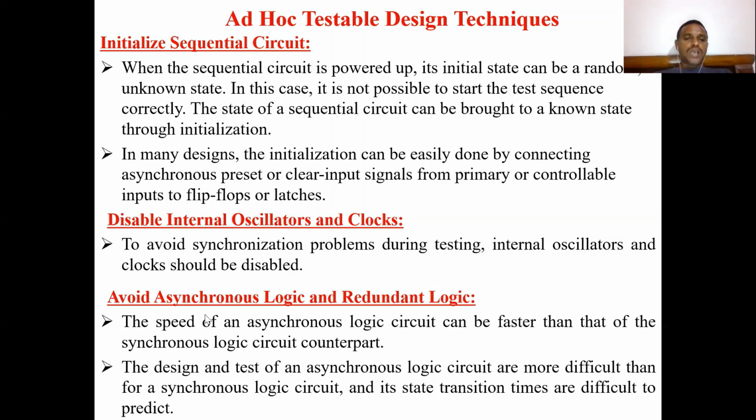The next one is to avoid asynchronous logic and redundant logic. If you compare synchronous and asynchronous circuits, the speed of an asynchronous logic circuit can be faster than that of its synchronous counterpart. However, the design and test of an asynchronous logic circuit is more difficult, and its state transition times are difficult to predict.